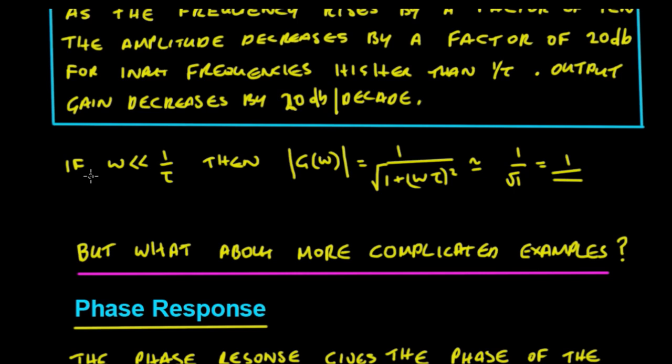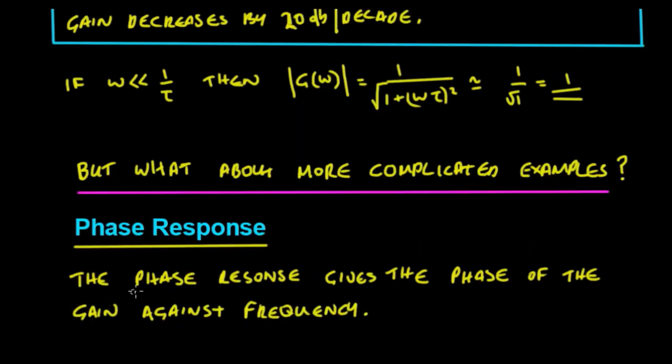amplitude response. Okay, at low frequency it's going to have a 0 dB gain, and there's going to be a cut-off point at minus 3 dB, so that's the edge of the passband, and beyond that the value is going to decrease at 20 dBs per decade. Okay, and that's just what we've seen in the previous drawings. Okay, so that's the amplitude response. Now, what about the phase response? We'll go and have a little look at that next.